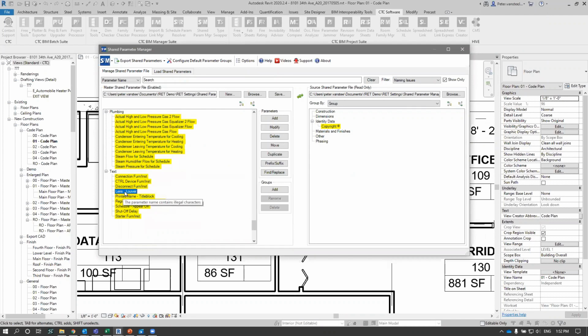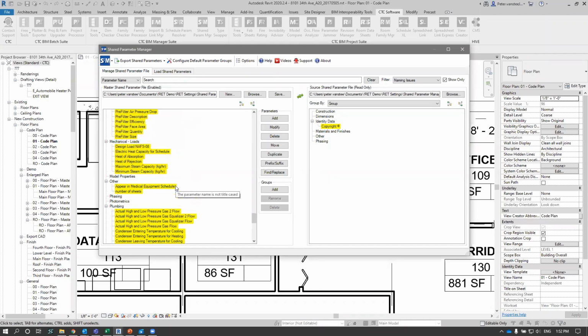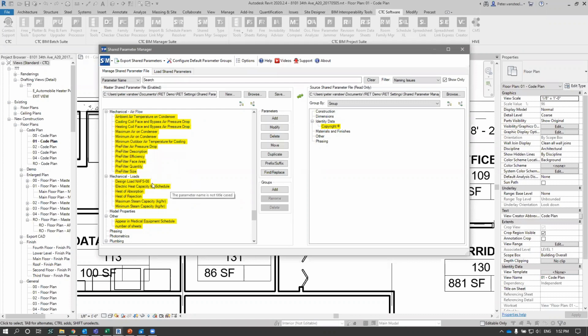Revit doesn't care that that's a hyphen. It looks at it and says, oh, that is actually the subtraction symbol. So lens minus louver, what is that as a formula? We can work around that, but would it not be a lot easier for all of our staff to simply start using families and not have to worry about whether my names are going to cause issues within project naming?